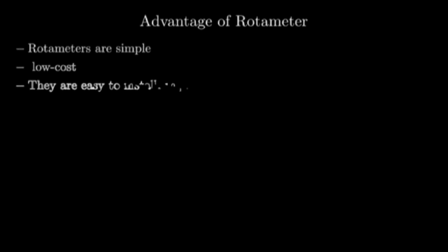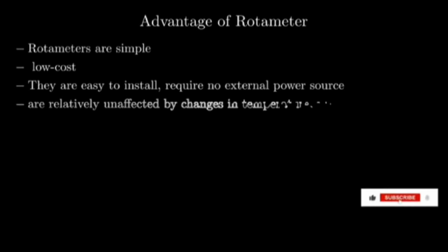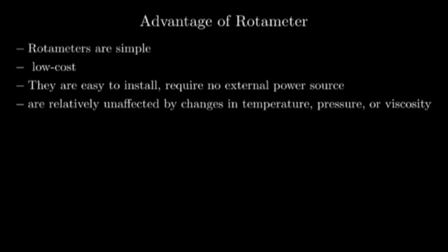The advantages of rotameters are that they are simple, low cost, easy to install and require no external power source. They are relatively unaffected by changes in temperature, pressure or viscosity.